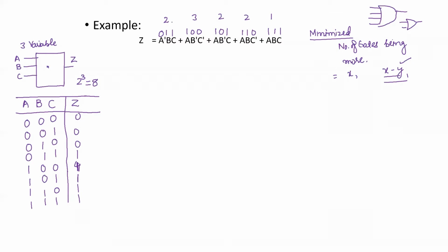As of now, if you assume we have access to multiple input gates, then you get correspondingly 2, 3, 5, 7, 9, 10. So you require 10 gates plus 2 OR gates, 13 gates. That is without minimization. When you implement a system using a Boolean expression without minimization, you end up with more logic gates, thus increasing the cost of your implementation. Also, the size of your device increases, the battery consumed will be more, and so many problems arise. So the best way is to minimize it.